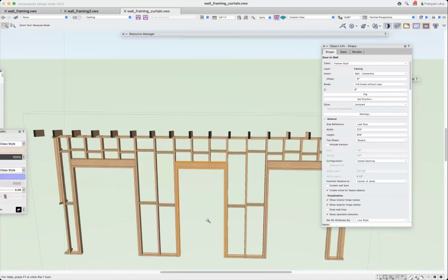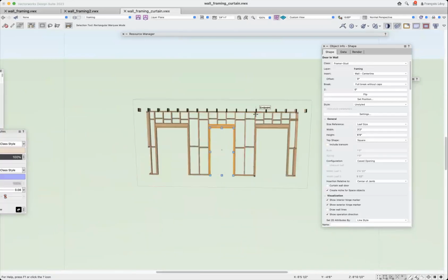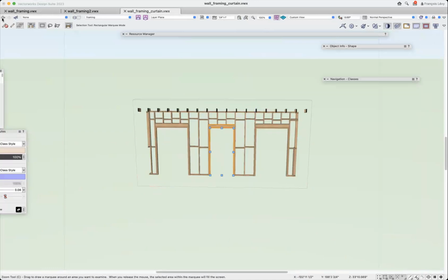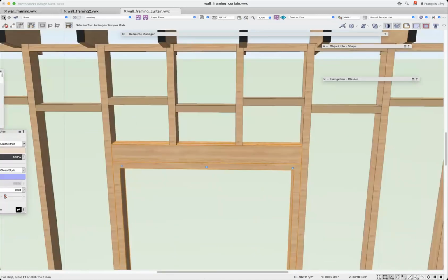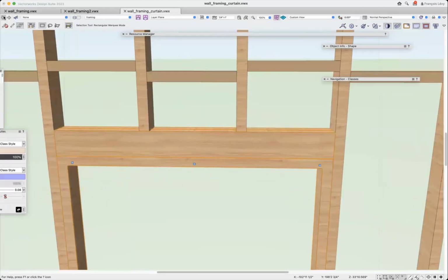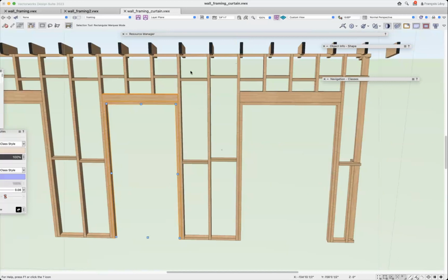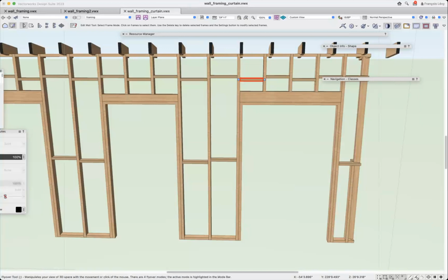But anyway, that was sort of a little exercise when I wanted to get really picky about my framing, is create this curtain wall style. And then my vertical blocking, these are just there, and I just sort of moved half of them up or down by 1.5 inches so that you could end nail them, obviously, as you would expect. So probably a little bit overachieving here on that one, but thought that would be fun to share.